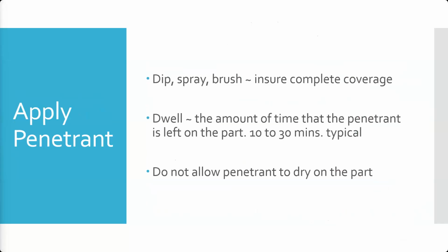Do not allow the penetrant to dry on the part. Like I said, we want it on there long enough to get in the part. We don't want it on so long that it dries and actually clogs the crack, or dries and is not able to be pulled back out of the cracks and crevices, which would prevent us from getting an indication if we had a relevant flaw.